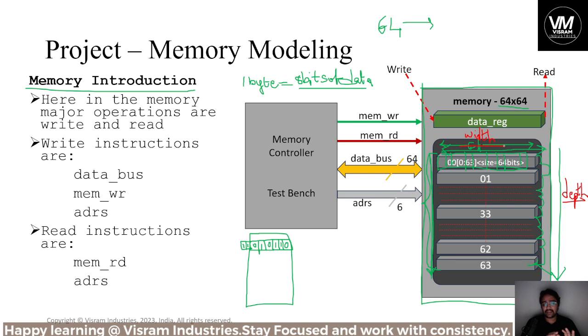Memory design can be in terms of different arrangements. It can be single port, dual port, or it can be a FIFO implementation as well. FIFO is nothing but first in, first out implementation. That's another design. I'd like to introduce it as a project, but those FIFOs are nothing but memory implementation, in terms of the output buffers or input buffers at buffer stages, like at the output of the design, like a bridge between the peripherals and the internal components of the architecture. So that is FIFO. I'll explain it in the next coming sessions.